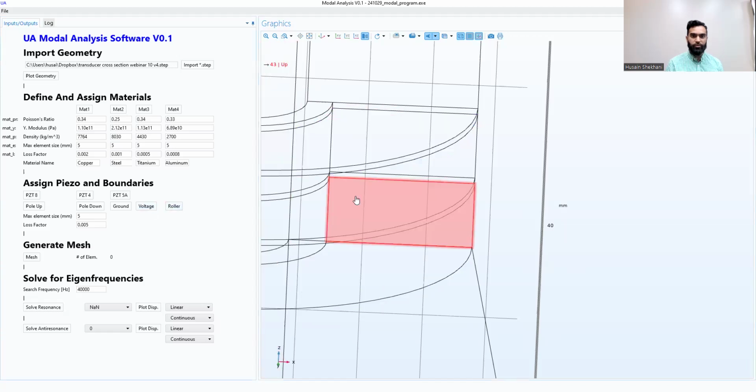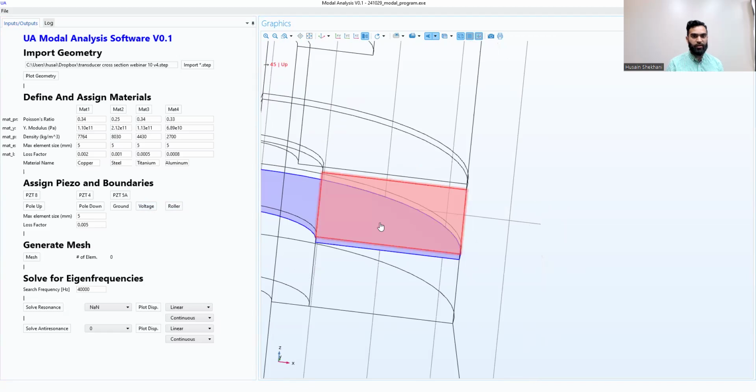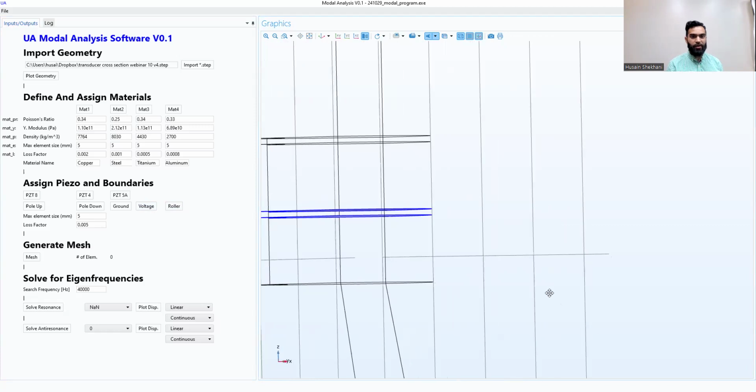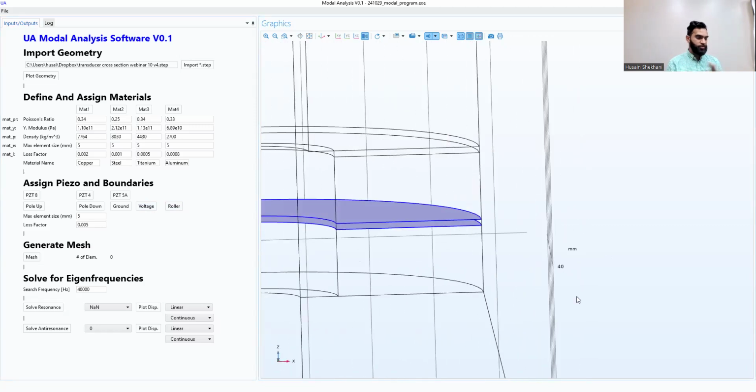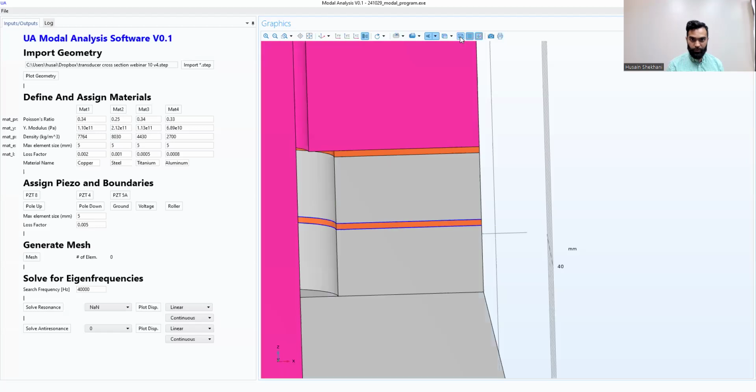Then for the voltage, where voltages would normally be applied, you have to select this voltage on the top and bottom part of the electrode. It's not like it's going to conduct through the electrode, so you would only assign it on one side in reality. This is simulation, so if you have no electrode, let's say you're making a very simple simulation, then you would just assign that one surface between the ceramics. But in this case, since there is an electrode of finite thickness, with a top and bottom side, you have to assign the top and the bottom with voltage. And we'll undo this now.